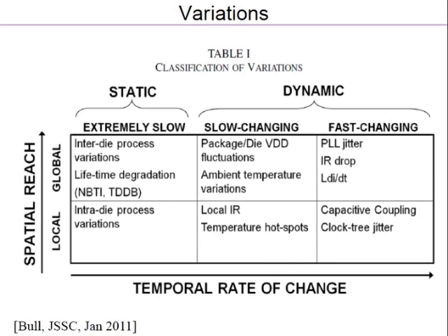It's a function of the doping concentration, the channel length due to short channel, narrow channel, and reverse short channel effects, the channel width, the oxide thickness, the materials, etc. And so there is always some variation. That is why threshold voltage is really the proper way of looking at it. It's a random variable which has a certain mean and a certain spread.